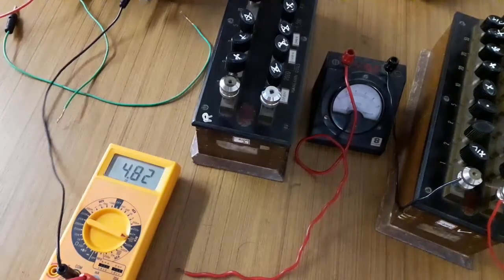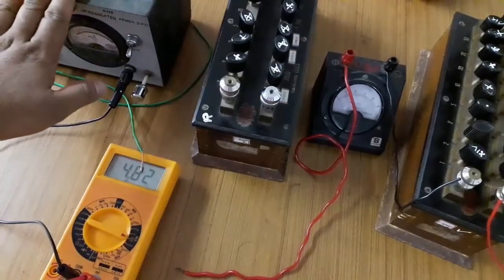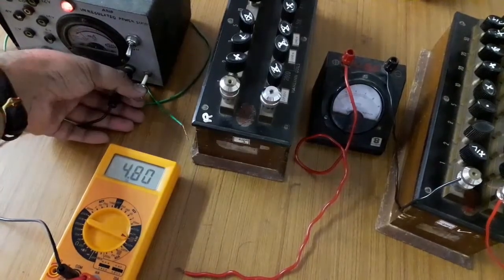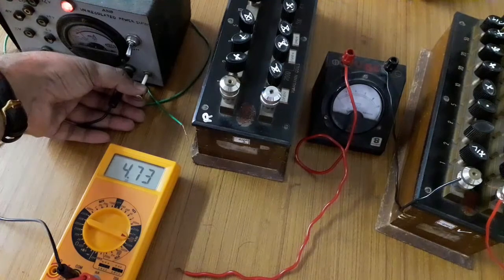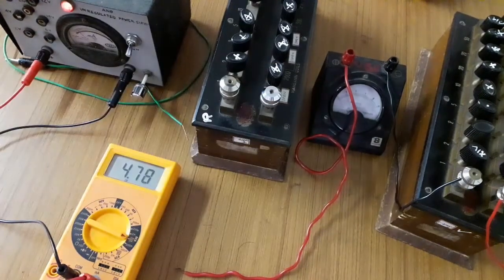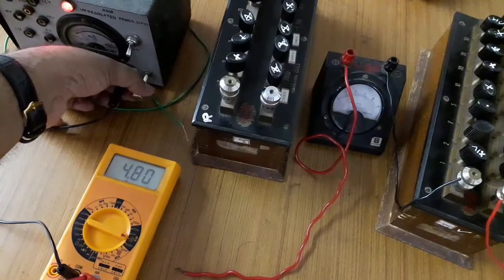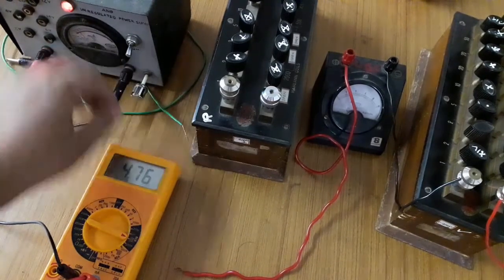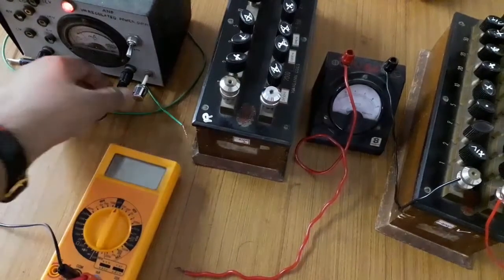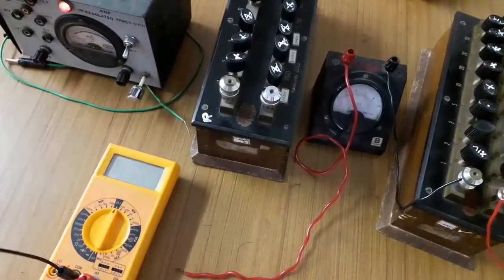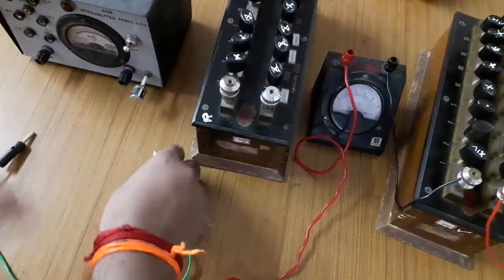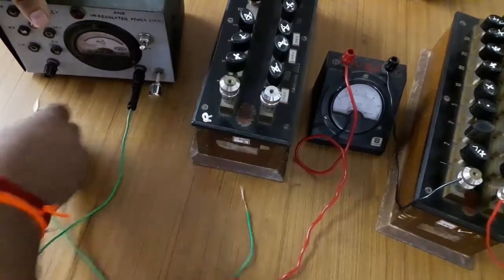Okay students, so I'm ready for the second part, in which we have this current source, and we need to adjust it. As we calculated, it is around 4.74. We will try to adjust it very near to 4.74. So this is 4.75. That's good enough. So let's use 4.75, or whichever is the closest one that we could get to. Okay, 4.74, that's great. I'll just remove this multimeter now. So our current source is ready. Let's switch it off, and let's keep the current source connected so that we can use it.